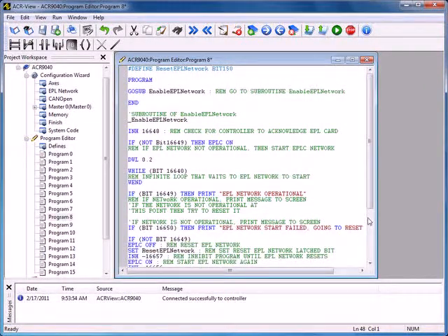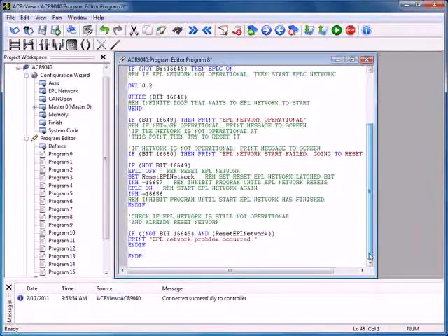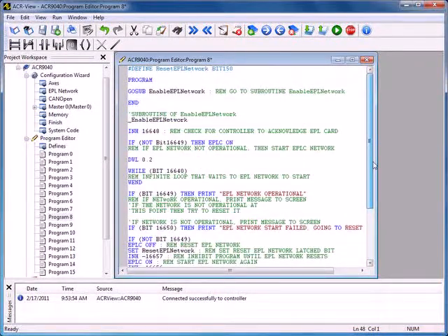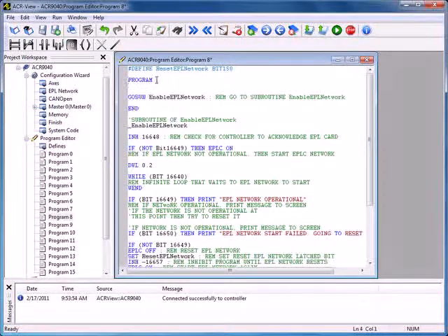In order to get this program to run on boot, we need to use the pboot command. So that's used to trigger programs to run on boot up. So right after the program, the first line needs to be pboot. So I'm going to put in my pboot command. So when I power cycle the unit, the first thing it's going to run is this program.